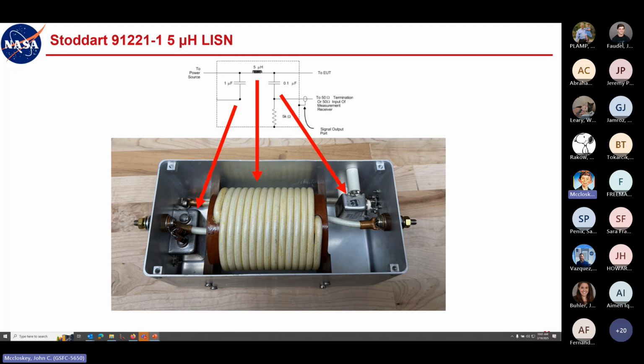If you have, let's say, 100 nanohenries per meter, and your power wiring is running 10 meters, then maybe you'll get a microhenry. But we almost never have 10 meters to the distribution point. That would be maybe 10 meters to a given load. But that's not what we're talking about. We're talking about what is the wiring to a distribution point, which should be much shorter than that.